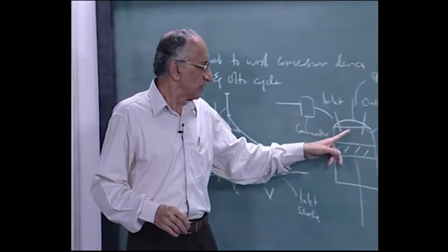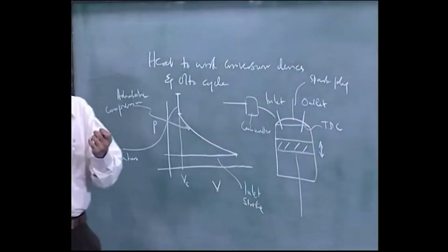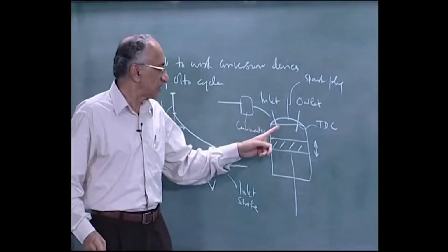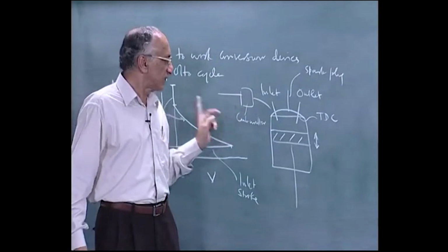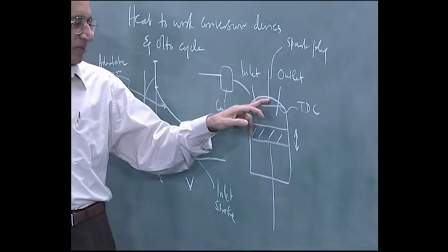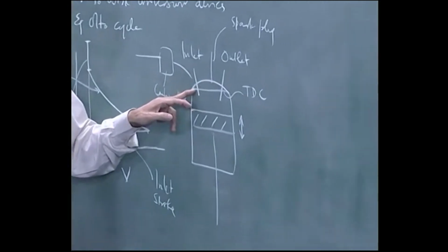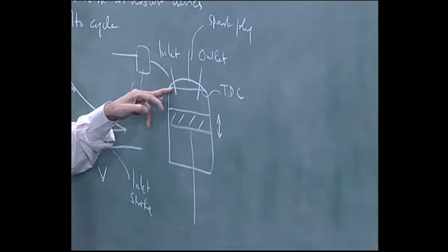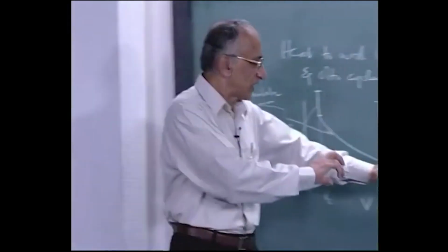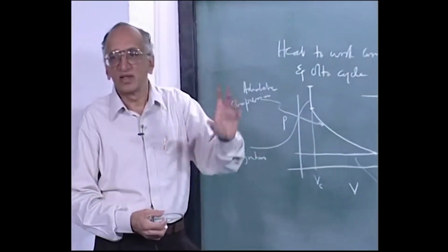Incidentally, this is what they will do when they tune a carburetor. They can tune the engine for you to get better acceleration. What they do is keep the spark ignition a little before the piston reaches the top dead center, so that the ignition occurs exactly when the pressure is maximum. It is measured in degrees because you have a dial on top which is turned. They will say 5 degrees.